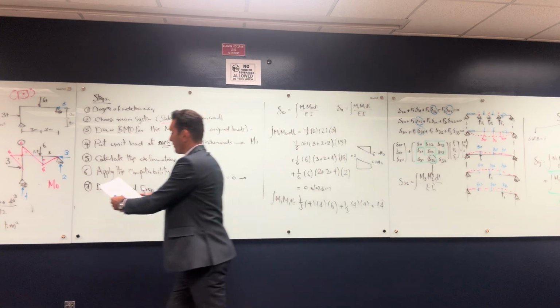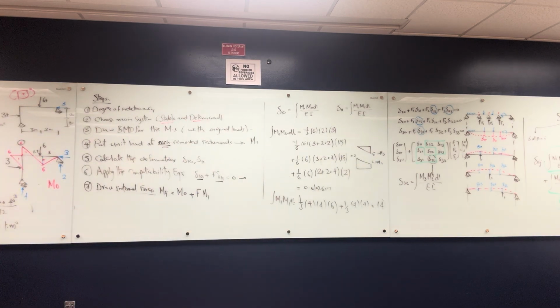How did I do that? I go here, triangle with triangle, this one, integrate this, and imagine that you have another beam that has the same bending moment. That's M1 and that's M1. Okay, this is 6 and this is 4. Integrate M1 with M1. So you integrate this triangle with this triangle. This is 4, right?